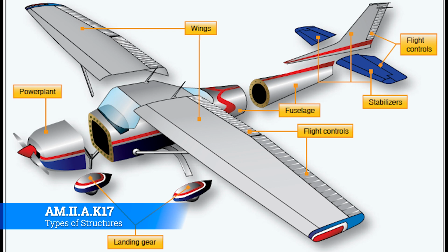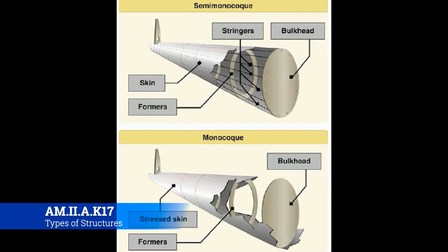This is when we're going to start getting into what monocoque and semi-monocoque are, so it's a good place to break that down. A monocoque simply means that there is one structure. The actual word translates as one shell. Now, if you look on that bottom graphic, you have the skin. I'll say it's a stressed skin, and then you have formers, and that's what helps hold the skin in its shape and its place. Those are formers, hence their name.